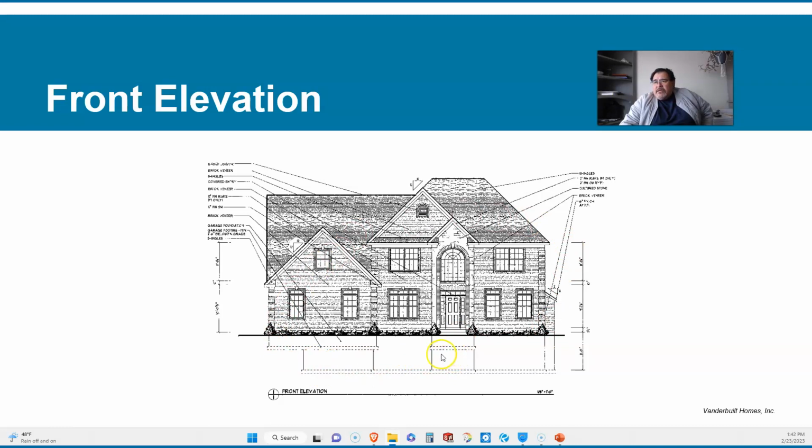You can even see below what might be what's happening underground. So this is the foundation floor for the garage that's happening on the other side. And this might be the floor for the basement that's happening underneath this lower level. So it's even showing you what's happening underground by showing you these hidden lines. They're showing you floors at different elevations, what they call footings.